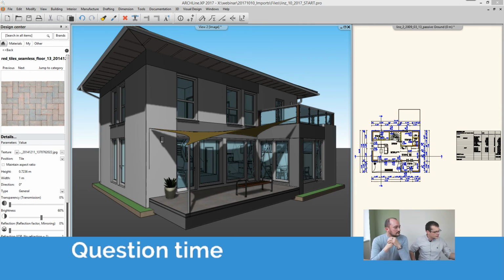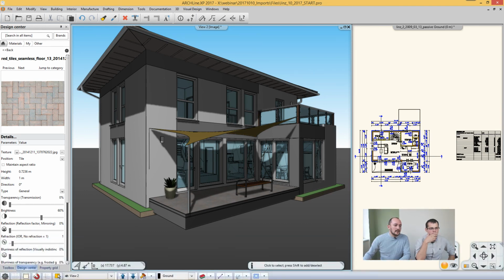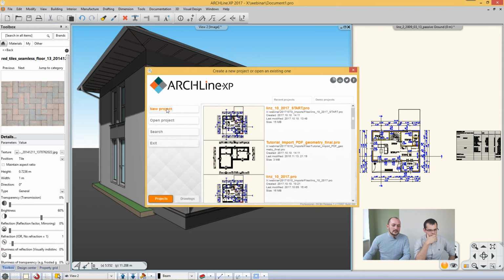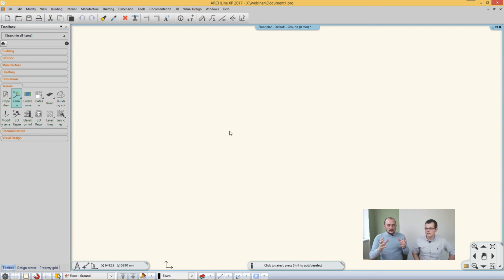That's right. And that's another follow-up question from Vanessa. Importing 3D files in a new drawing and saving them as manufacturer objects seems to keep the drawing lighter. Is that a good way? Yes, that's a good thing. If you import something into your project, sometimes these items are not just single items. Let me show you that. This is a good practice Vanessa is mentioning. You open up a new project, you import the data into that project, and decide what you would like to keep.